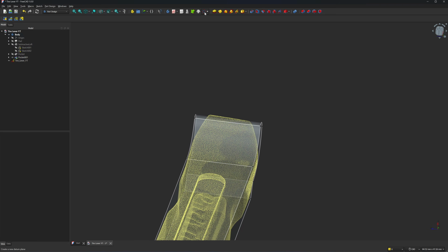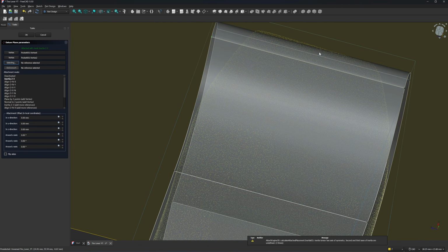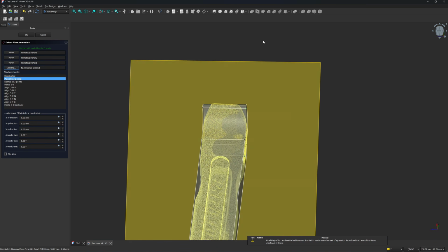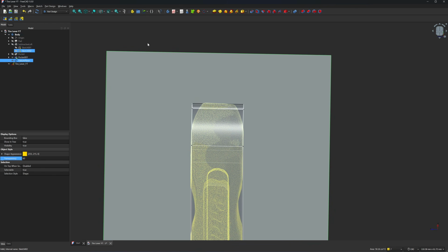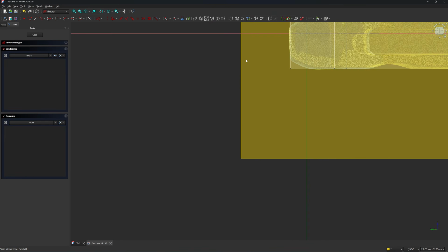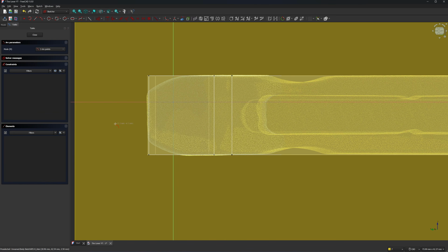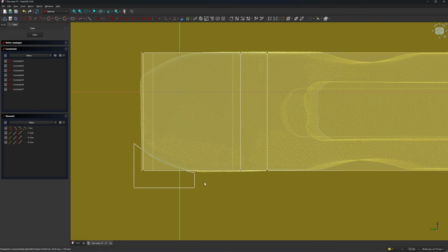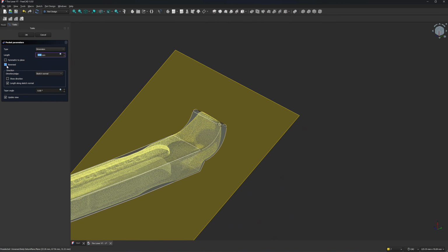Doesn't matter. So I will create a plane using a datum plane function. Okay, so I click on 3 points. I will create the plane for making a cut. I click on here. Let's click on OK. Click on the plane. Click on the sketch. So I will create this cut using arc, 3-point arcs, 1, 2, and 3. Move it here a bit, and I'm going to cut this. Close, pocket cutting, reverse, side 8.